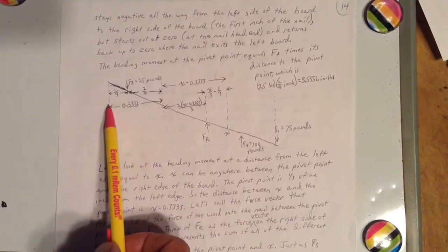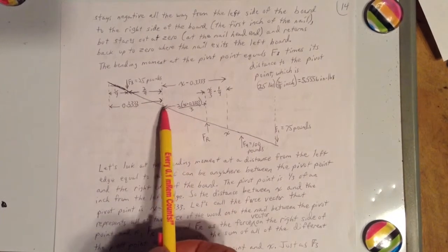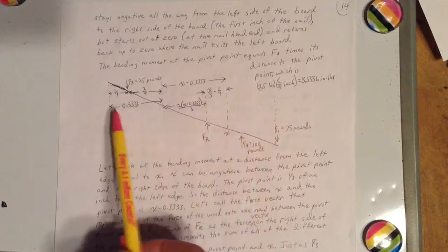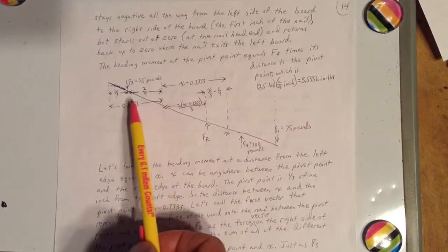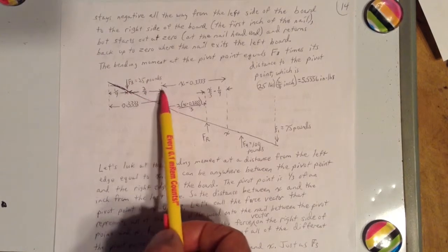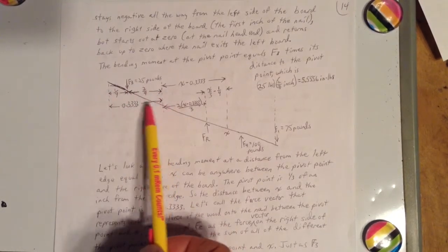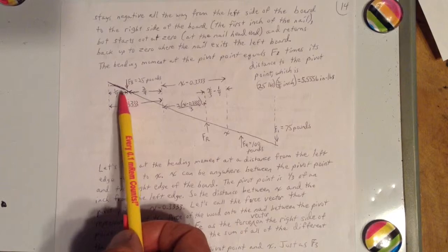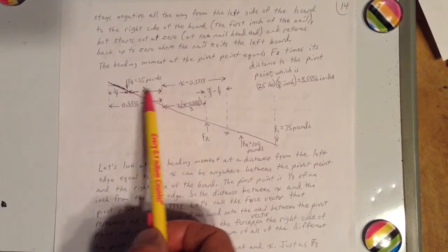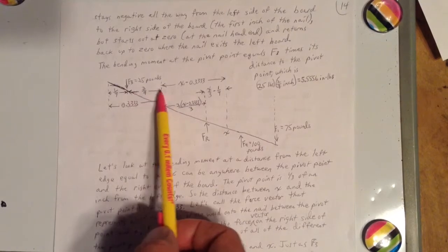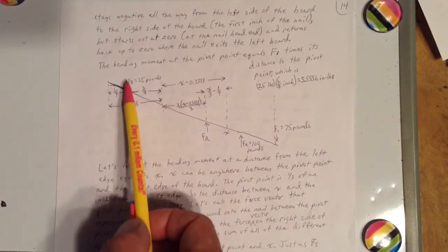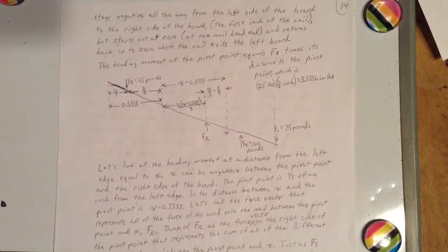We determined that the distance from the left edge to the pivot point was 1/3 of the way across, and this is a 1 inch board. So if that's 1/3 of an inch, and this F3 is 2/3 of the way from there to there, well then it's going to be 1/9 of an inch to there. It's going to be the other 2/9, 3/9 all total, which is 1/3. So it'll be 2/9 from there to there, 2/9 of an inch times 25 pounds,